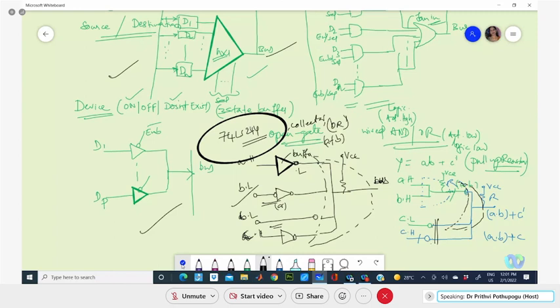For one pressure applied on the button, let it be any duration, however long the pressure is applied, only one pulse has to come out. So wait till that pressure is released in order to go to the next iteration.